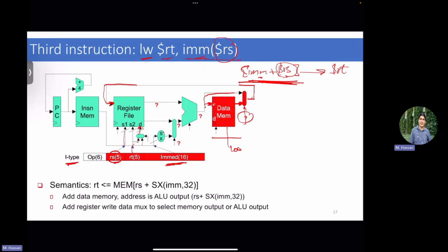This becomes a little bit complicated when we discuss pipelining. There is a clock frequency, and then if I have a data miss, what are the consequences? So we go to caches, right? But that's a step-by-step discussion. Here, any functional unit takes whatever time it needs. I wouldn't say purely combinational because there are sequential elements, the register file and data memory, but I am executing a single cycle processor where you take all the time you need. Frequency is not a problem. Okay. That's a good question.